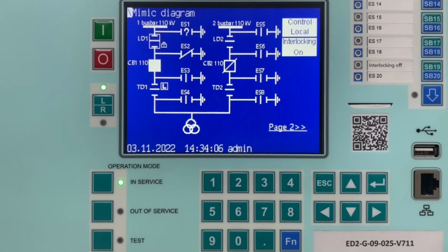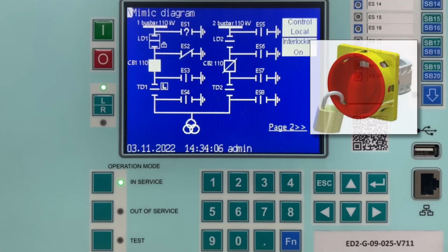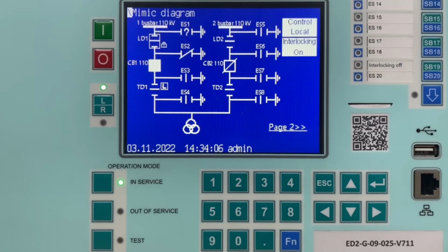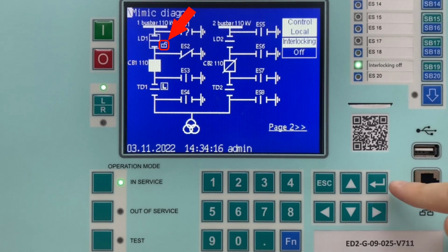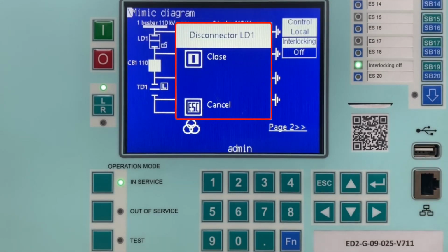For security purposes and to prevent unauthorized entry of emergency unlocking when working with electronic switches, authorization with a password is provided, and when using the operational switch, it can be possible to install a seal or a padlock with a non-standard key. After applying the emergency unlocking, the symbol in the form of an open padlock will be displayed on the mimic diagram, and control of the switching device will be available.